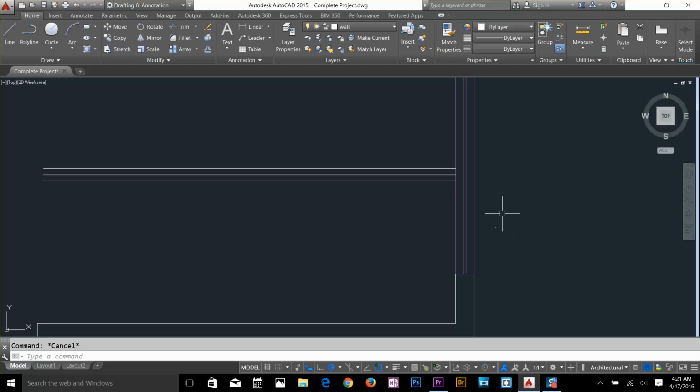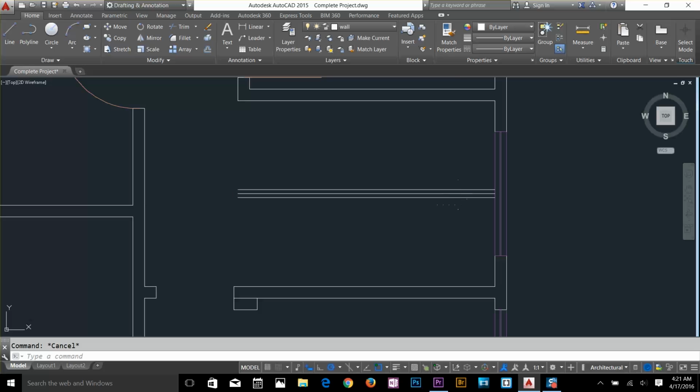So now draw another line. Let's see what we got. Alright, now we've got that, so just delete that middle line and give an offset of 2 feet, and grab that vertex and just drop it there. Or you can actually extend that and then trim off these lines.